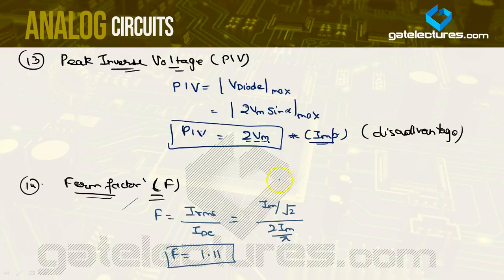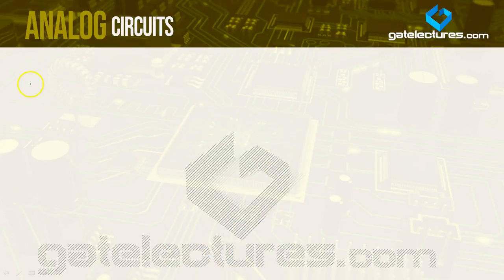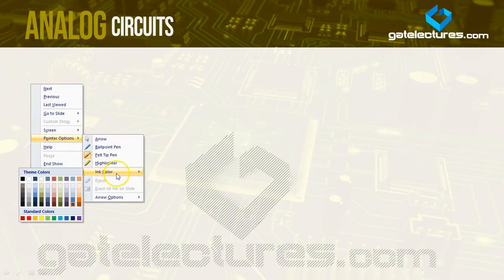This form factor value was 1.57 in the case of the half wave rectifier, and ripple factor was 1.21. So here the ripple factor has reduced drastically in the full wave rectifier as compared to the half wave rectifier, because it is equal to 0.483 in the full wave rectifier and 1.21 in the half wave rectifier. Form factor is also reduced. It was 1.57 and it is now 1.11. These are the major differences that you should know and be able to point out.